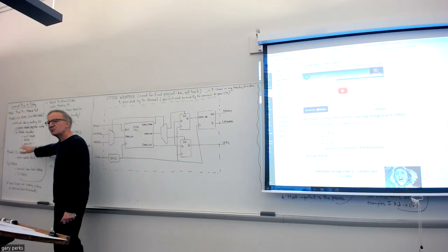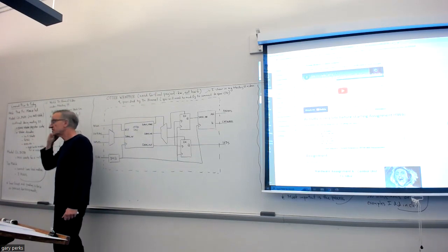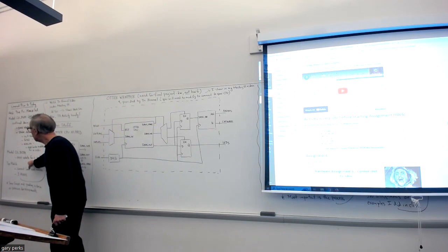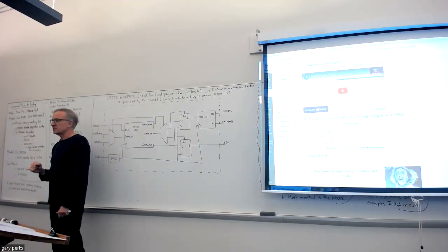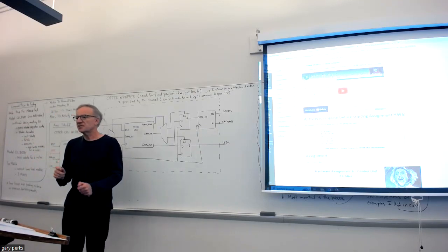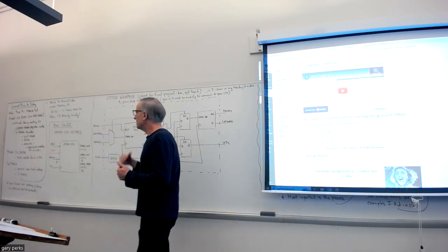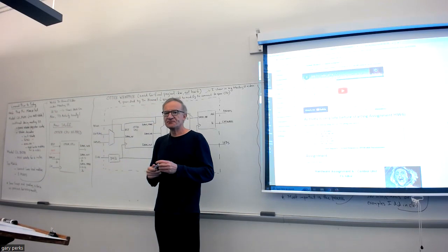You're going to have to modify the execute state of your state decoder, the FSM, because you're going to need the read-write enables for all instructions. And then for the control unit decoder, you're going to need the mux selects for all the instructions. Okay, we'll talk more about that coming up when we get to the final project.